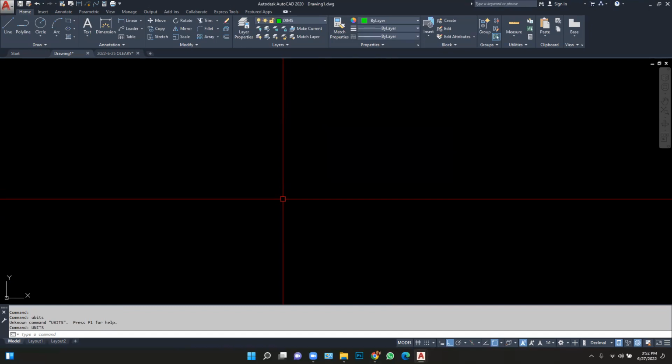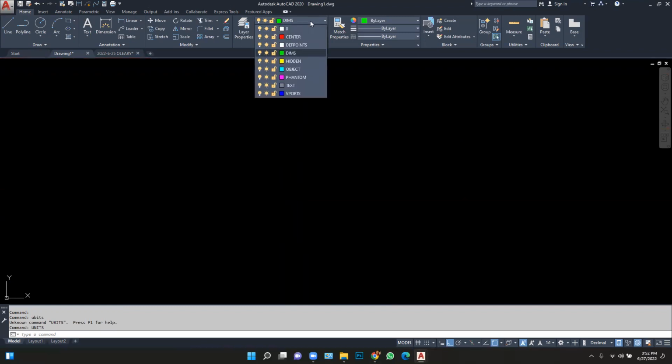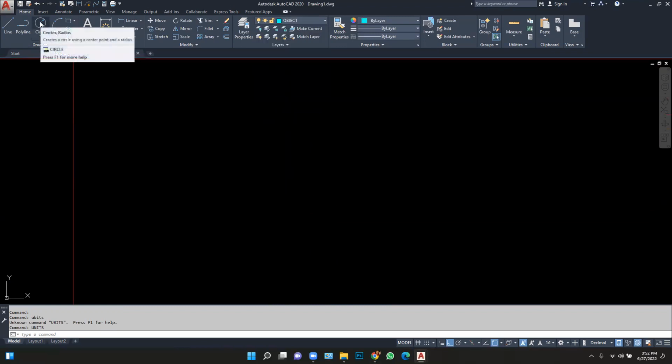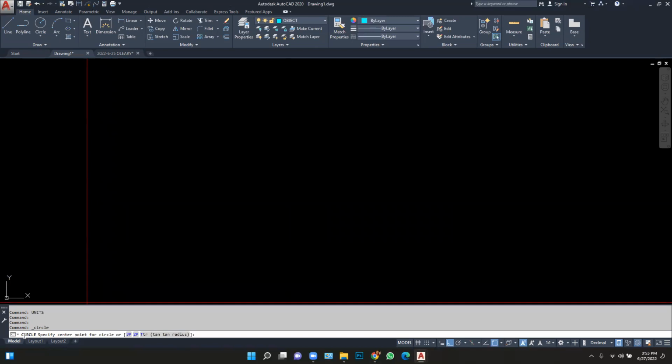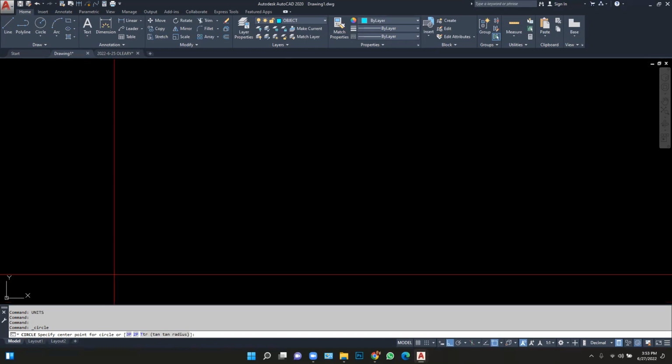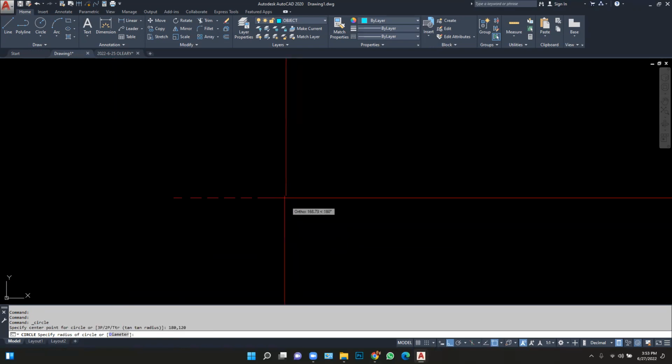Keep the remaining units command default values. Begin the drawing. The center of the 150 millimeter diameter circle at the absolute coordinate 180, 120. So I'm going to put object as my current layer. Pick the circle command. And at the command line, it's saying circle, bold, uppercase. So you're in the circle command. So that's what that's signifying. After that, it says specify the center point for the circle. The direction just told us the center point is 180, 120. And then you hit enter.